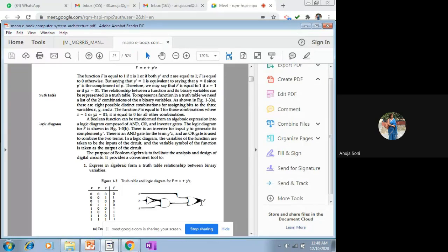And ultimately, this plus operator, which corresponds to your OR logic gate, is used, and over the 2 operands, one is your x, another is your y dash z. So y dash z is coming out from this AND gate, and from another side x is coming out, and these 2 are inputted in your OR gate, and ultimately it results in the final function value f.